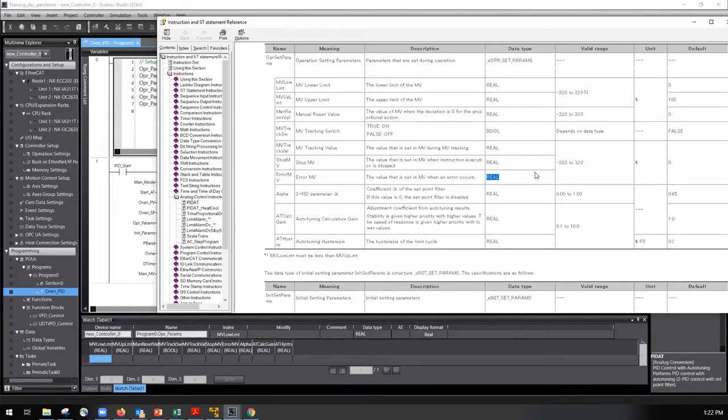On our distribution side of things, you never want your distribution to stop. That means you have to issue a boil water advisory, and it gets messy, paperwork. So I would have a value that would allow distribution to keep going, keep our distribution pressure up, but it wouldn't be controlling itself. The PID loop would be just holding that value until we could figure out what was going on.